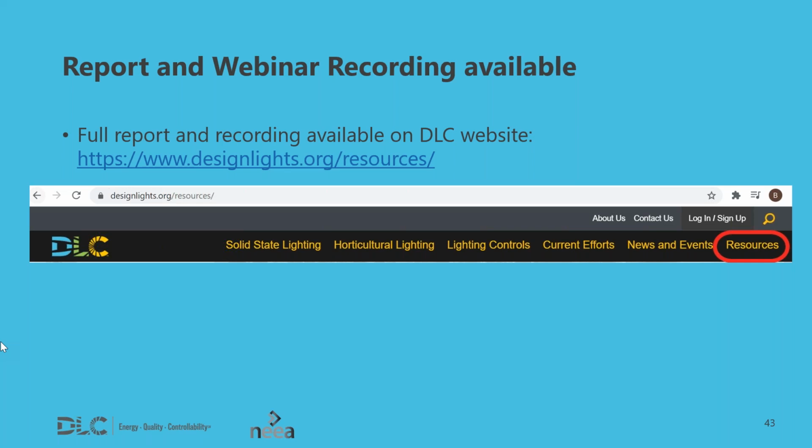So High-End Trim is one of the controls capabilities where, during the commissioning or startup process, when the luminaires have more light output than you want, or than the occupant needed, or than the design specified, then you can trim it down so that when you use the wall switch or wall dimmer to turn the lights all the way up, it won't go all the way to the full amount of light it can provide.